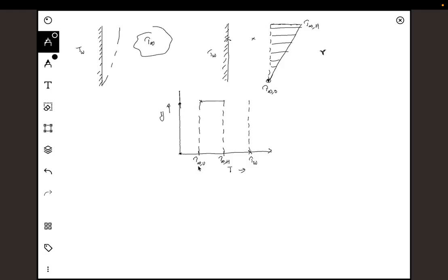But then TW is something different. So the extent of this compared to this, basically T infinity h minus T infinity 0, would be one parameter which we will define shortly. This indicates something related to the strength of stratification.